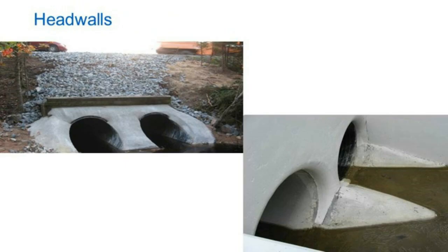And here we're going to look at a couple different headwalls. The length of the pipe was calculated so that they had enough pipe to cut those slope ends back and then place concrete slope protection around there, below their riprap, to prevent any erosion against the grouting or the annular space of the pipe.